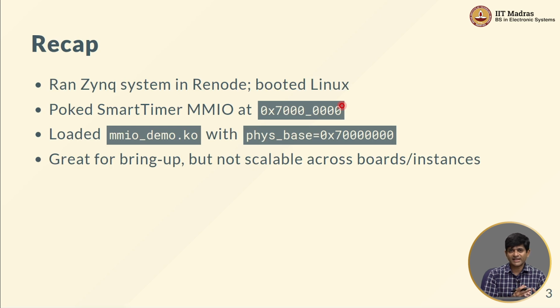How does that work? Basically it detects that this address has now come onto the bus and it makes some internal changes inside the hardware. So I clearly cannot go around randomly searching all the different addresses. As a hardware designer, I need to know which address I have connected the system at, right. My module, whatever it might be, my smart timer, a UART, or an ADC driver for some custom software defined radio project, for each and every one of those, I need to physically know where exactly I have connected the device.